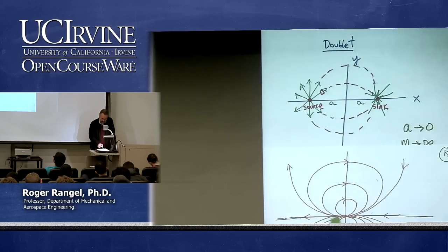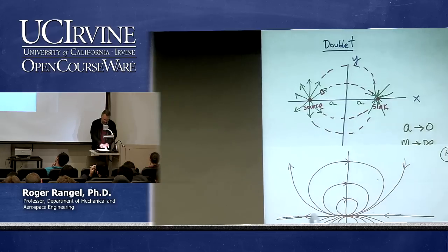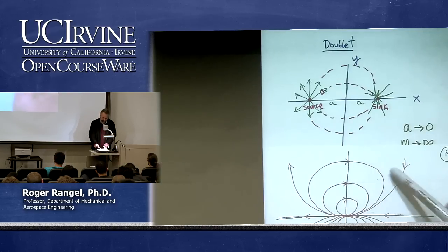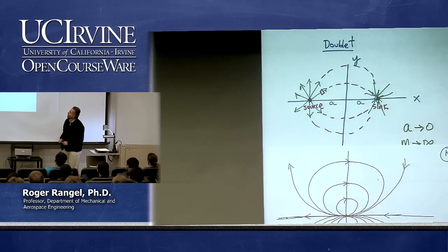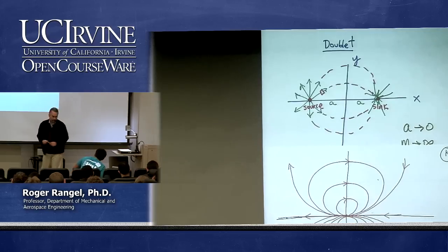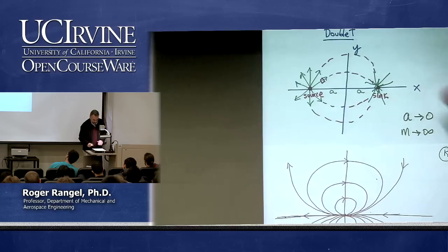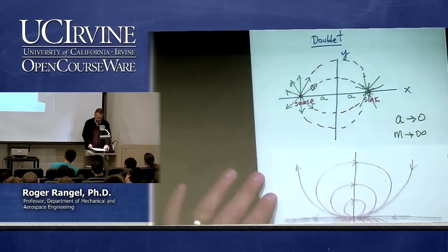So it is not surprising that towards the left side the flow is going out. That's why you see these streamlines on the left side, they're all going outwards. Of course they are going around just like they were here. And they end up at the sink, which is also at the origin, but it came from the right side, so not surprising again, we see that the streamlines are coming in through the right side. So that is what the streamlines look like for a doublet.